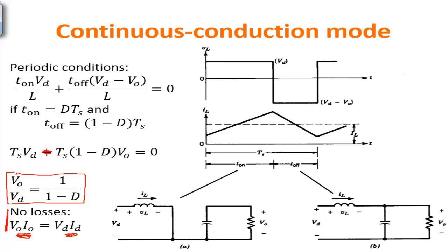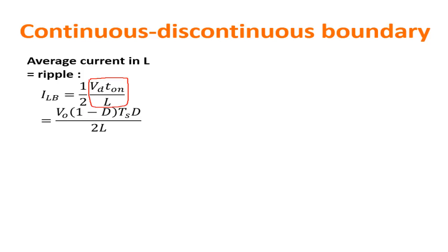As you can see, also in this case there's the issue of discontinuous conduction, because if the current absorbed by the load decreases, then this dip here can touch zero, and then you are at the limit of continuous conduction, and one has to do considerations similar to the ones that we did before. What are these considerations?